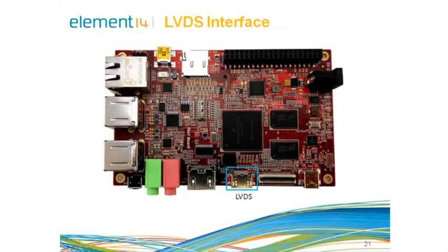It has an LVDS interface. LVDS is low voltage differential signaling, and as we know, LVDS operates at low power and can run at very high speeds using normal cables. Hence, we can connect any kind of LVDS display on the board. We can connect one port up to 165 megapixels per second or two ports up to 85 megapixels per second, for example, WUXGA at 60 Hz each.